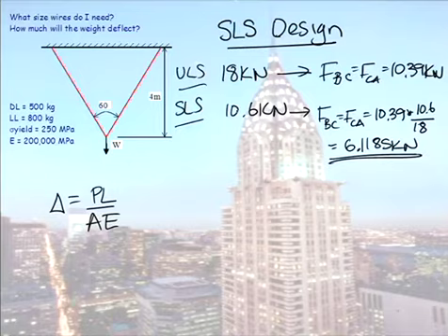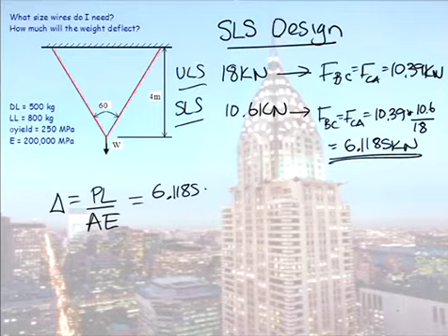Now, this formula works out how much the tension is going to stretch this time round. That amount of stretching is of course not the vertical deformation, it's the amount the cable is stretching. But we'll work out first how much our cable stretches. And I'll just stick to 4 decimal places if that's okay. Always use more rather than less and then round off at the very end. There's my advice to you.